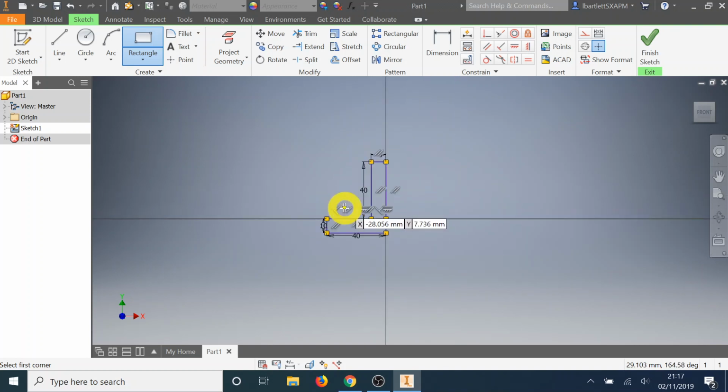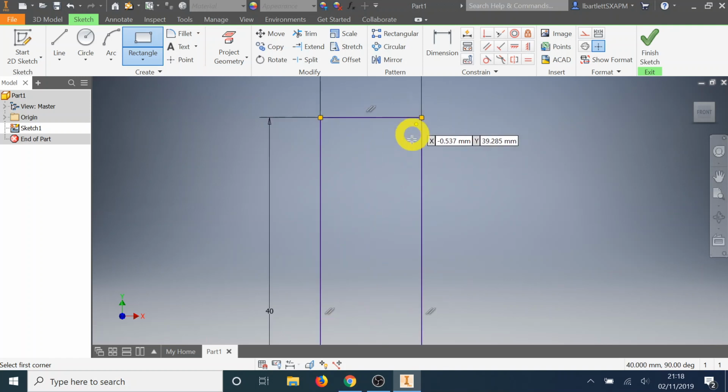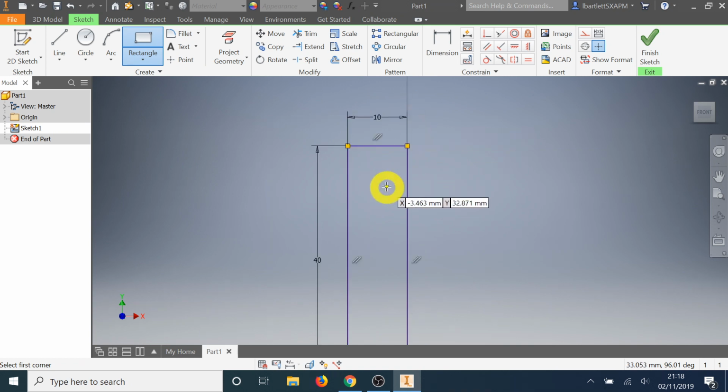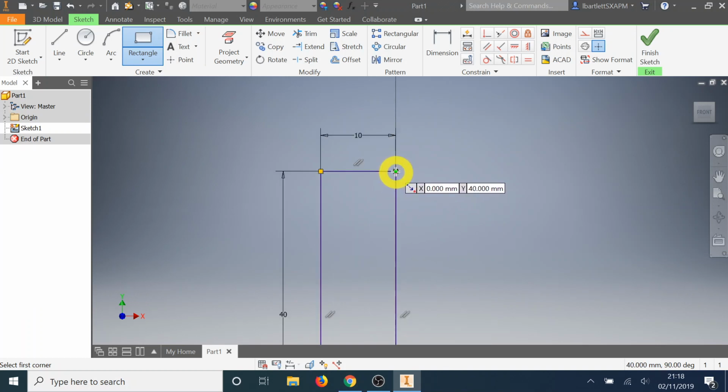There we go. And I'm going to do my third box. My third box, I want to start it on this corner here. I'll zoom out so you can see what I mean. So there's my shape there. I'm going to go to this corner here. I'm going to make sure I get that green dot. If I haven't got that green dot, put your hand up. Okay, so click there on the green dot once.